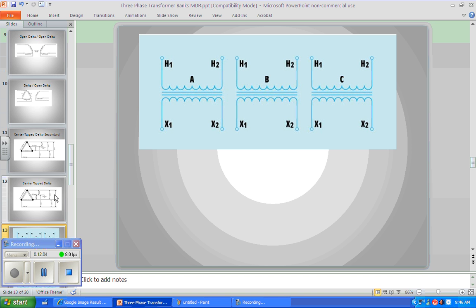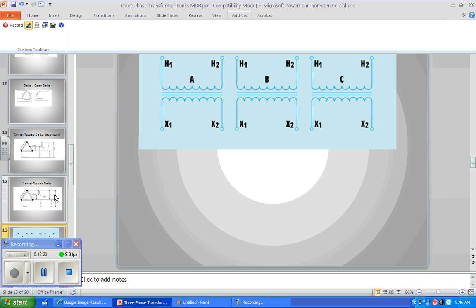Okay? But first we want to be able to get the voltages going down and then get our currents and start going back up. So let's do a, what did I say we're going to do first? Delta Y delta? Yes. Okay, let's do a delta Y delta. Here we have our drawing. We're going to connect our primaries as a delta. So we're going to tie these two together. Remember that the delta looks like this, and we're going to wire it like this. We want to wire from corner to corner, and we're going to tie the primaries into where it comes in.